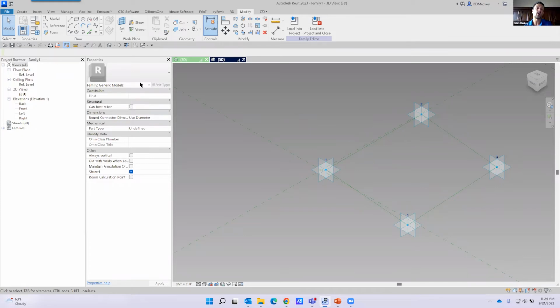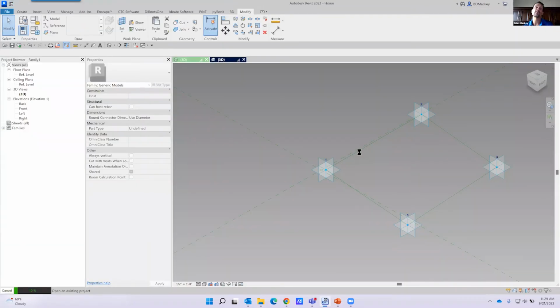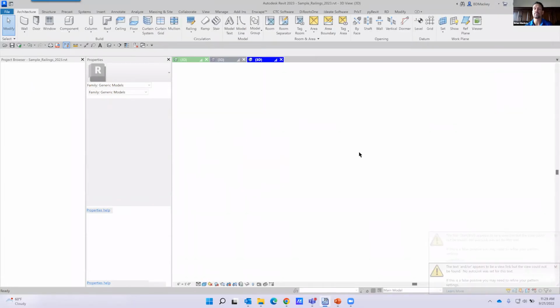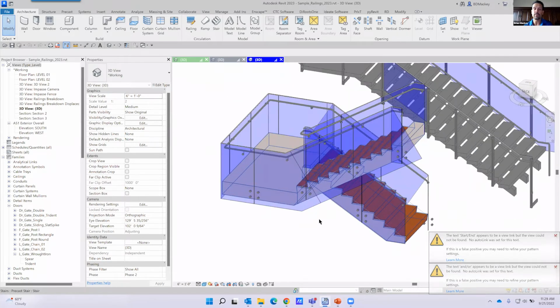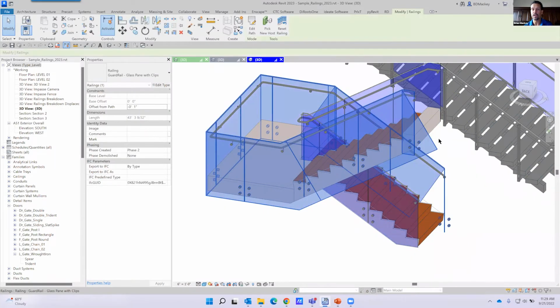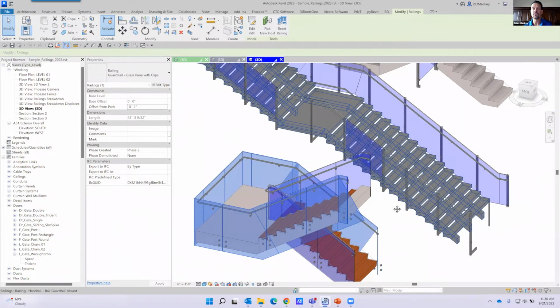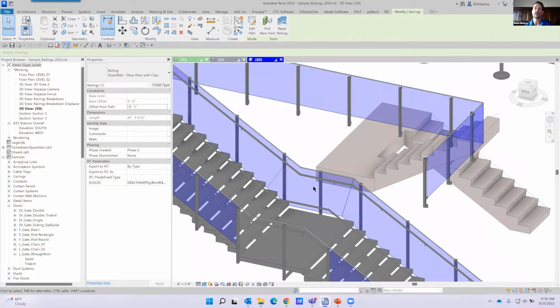Now, another thing in my repertoire is I have my own 4-point panel, right? And I use this 4-point panel for numerous things. One of the biggest things architecturally people get upset with is the Revit rails. If we're trying to do Revit rails in a glass panel scenario, right? So if I come in here and look at this, if we try to do Revit rails with a glass panel, if we do it as a sweep, you can end up with crazy things like this. If we do it as a panelized system, the panels might overlap at the end and you start getting weird scenarios.